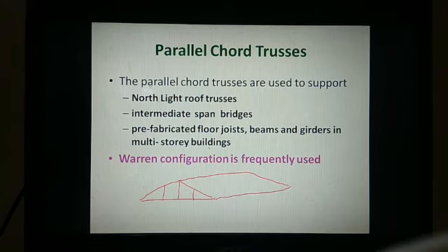To connect these two trusses, for the purlin, instead of an angular section or beam sections like I section or C section, I can make use of a parallel chord truss to connect these two pitched roof truss members. This purlin can be used as a parallel chord truss, where it can accommodate more spans, so more bay.